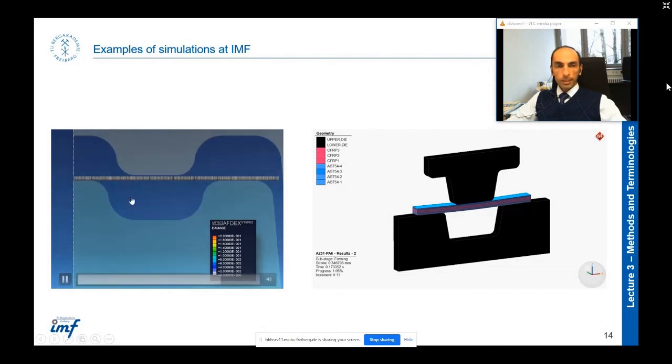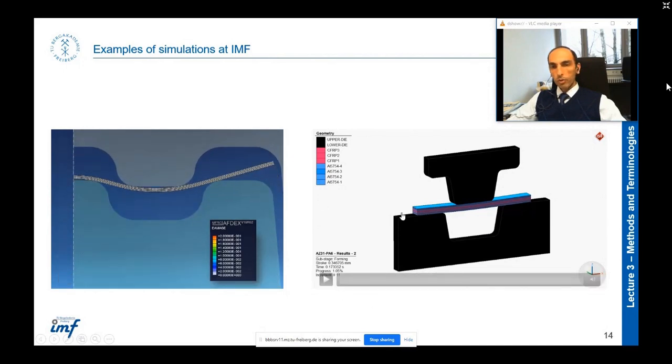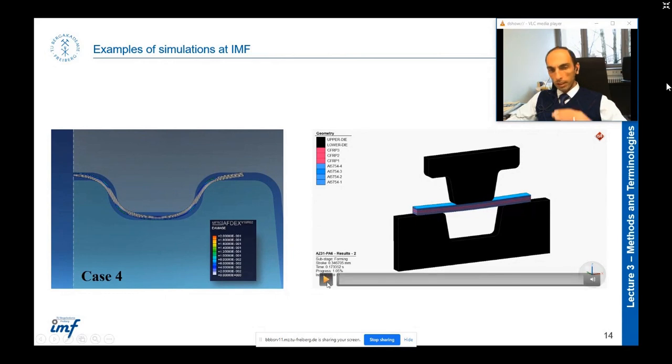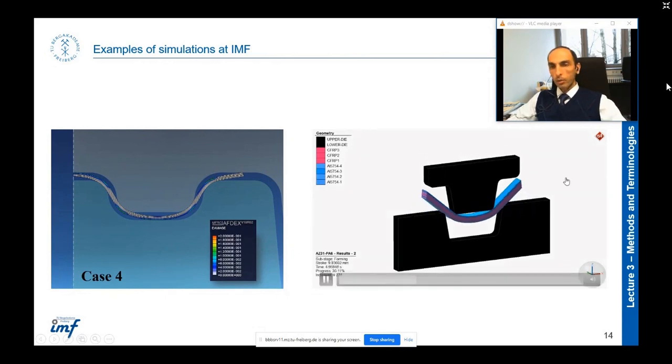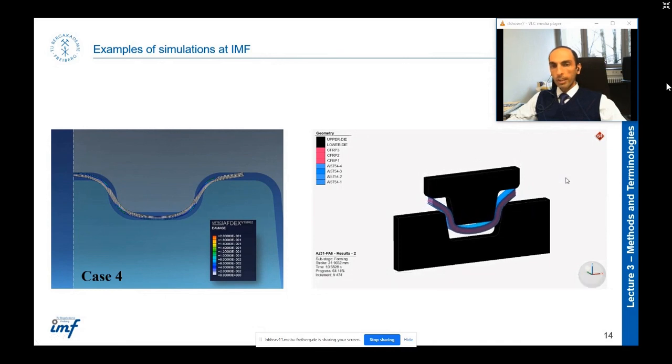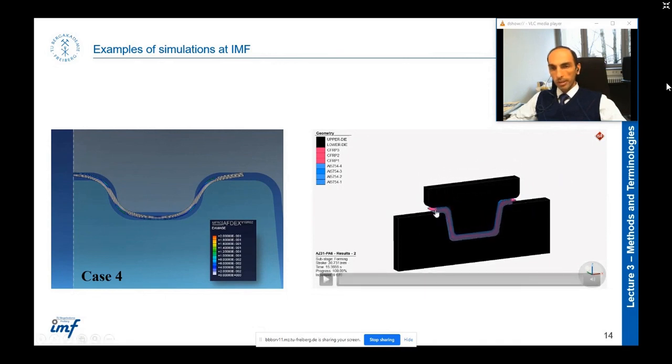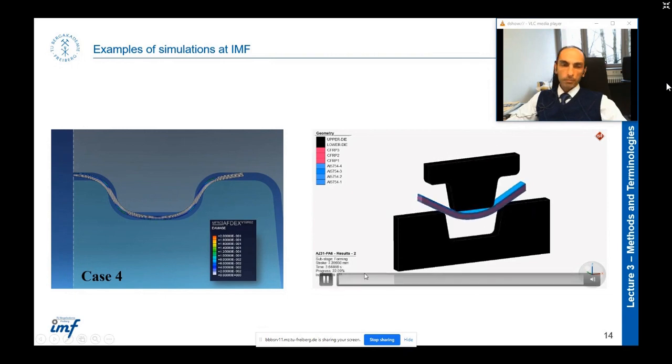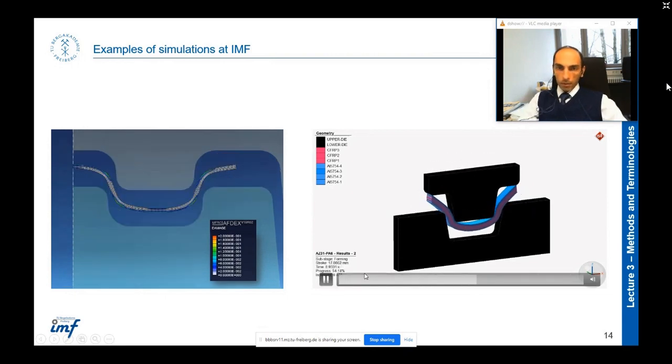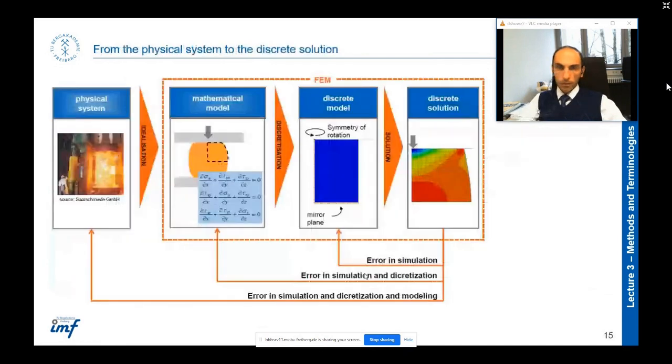And then this plate was from magnesium. Then it goes into another process, becomes a composite with the polymer and the aluminum or magnesium in a layered composite. Then we simulated all together how it deforms and how it behaves and how the polymer escapes from between the metal plies. Okay. So many examples, many practical cases.